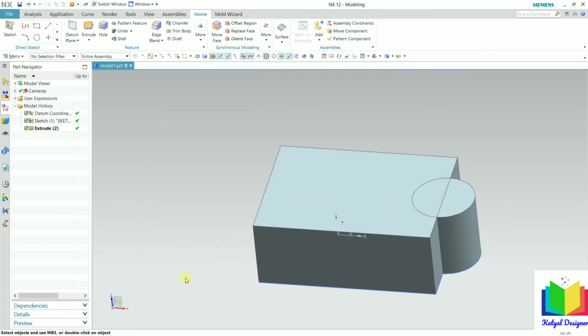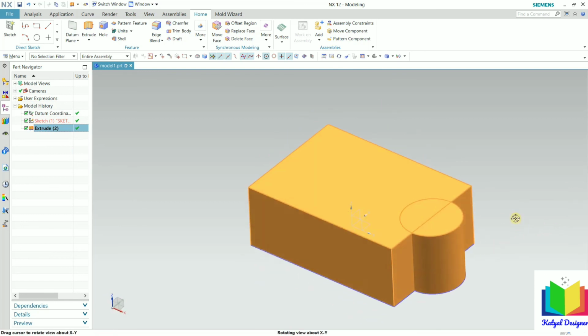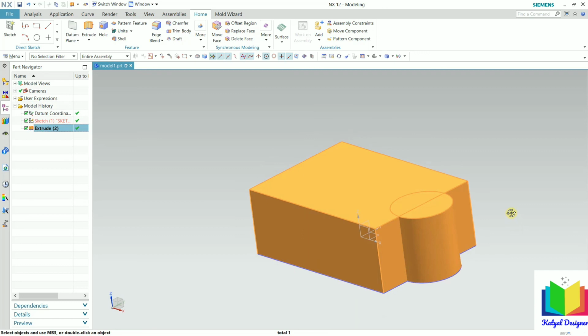The reason is that, see, both the extrudes have come in the single object. So these are a single object. So both these two geometries are a single object. And sometimes after we create a complete geometry, we need to edit this. And it is not possible to edit this type of geometries. So that is why we should always avoid the intersection or combination of geometries.